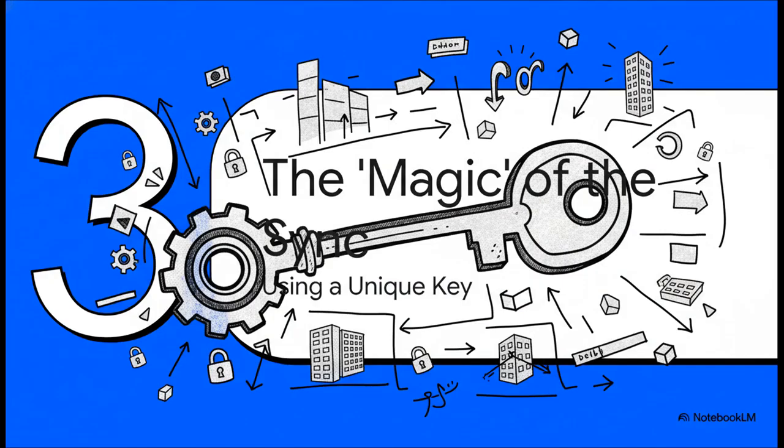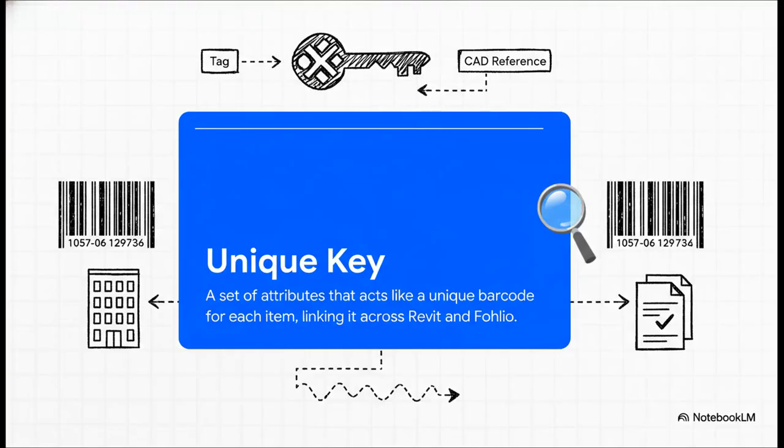So we've mentioned this unique key a couple of times now, and let me tell you, this isn't just some minor feature. This is the engine that drives the entire sync. It's where the real magic happens, especially for those flexible, spec-driven workflows. The best way to think of this unique key is like a digital barcode. It's just a single, unique ID, maybe a tag or a CAD reference, that you attach to an item in Fohlio and to its matching placeholder family in Revit. It's the exact same barcode in both places.